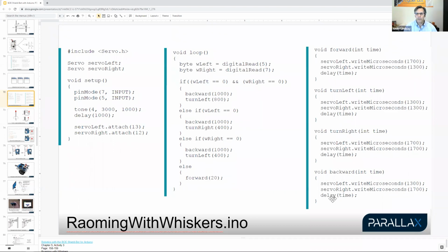And I threw out the term interrupt service routine earlier. That's what's happening under the hood: a certain number of times a second, it's checking to see if it needs to send that every 50th of a second pulse to keep the servo on track with what it's doing. So that's multitasking, and it does work similarly from the coding standpoint to multiprocessing.